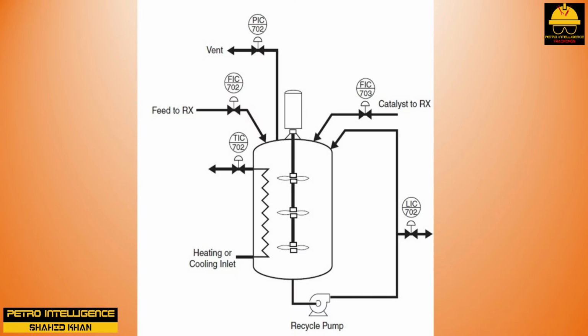Stirred reactors are equipped with a number of safety features: pressure relief systems, quench systems, process variable alarms, and automatic shutdown controls. Quench systems are designed to stop the reaction process. Pressure relief systems are sized to handle and contain any release from the reactor. The relief system may be designed for liquid, vapor, or a liquid-vapor combination. Safety relief systems allow process releases to go to the plant flare system. Sometimes a chemical scrubber system is used before a product is sent to the flare system.